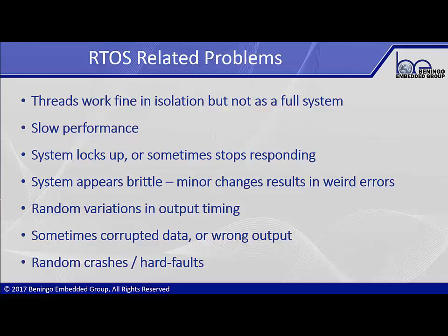This tells you that there's some problem with the way your system is synchronizing. There could be something more going on here. We may find that the performance of my real-time operating system is really slow. It's not behaving the way I expect it to. Now, a lot of times people who come from the bare metal world will say, oh, an RTOS has so much overhead, they're horrible, you shouldn't be using them, super loop forever kind of thing.